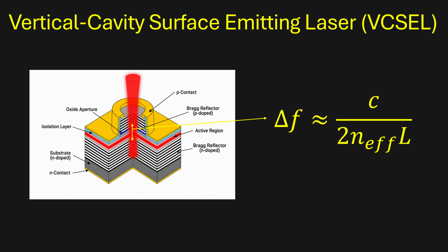The round-trip optical path length of the cavity, which is the actual length times refractive index, is set to match an integer product of a desired free space wavelength, usually 850 nanometers. This produces a resonant constructive interference for that specific wavelength.